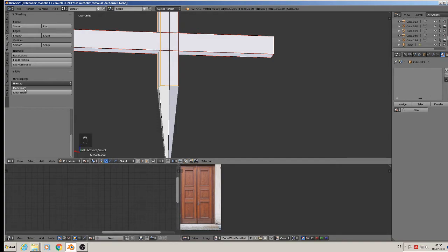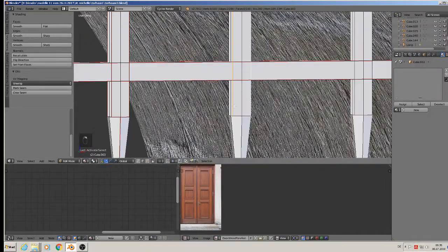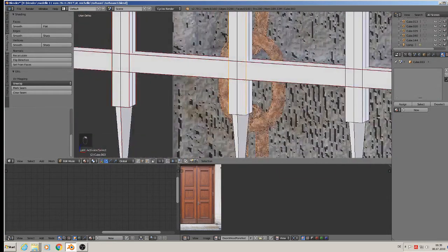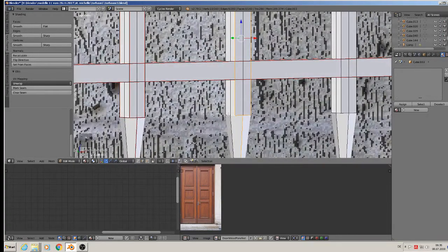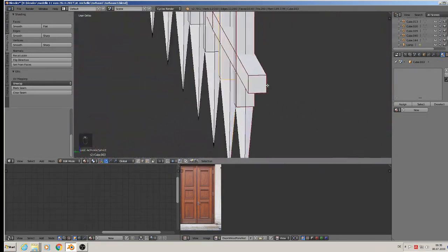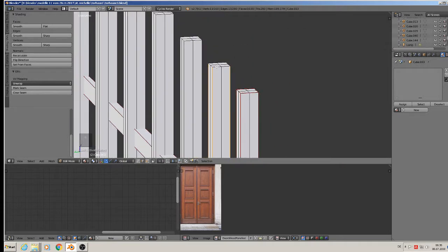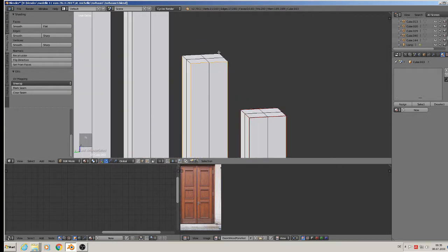Best is now set wireframe mode. Then you haven't that problem, because all is transparent, or like transparent, you know how that looks. And we mark here down line, top line, and to the tip. So mark seam.